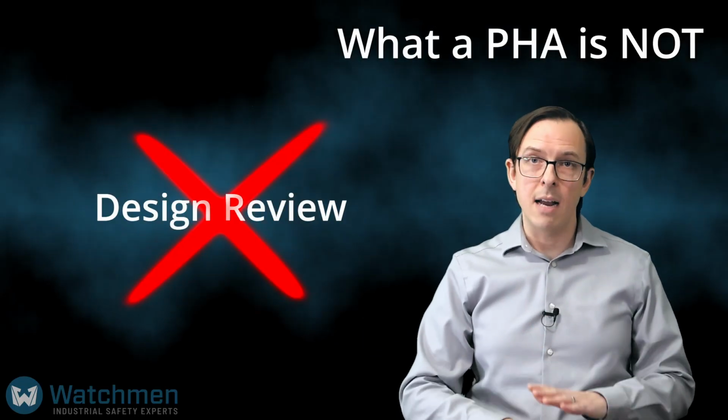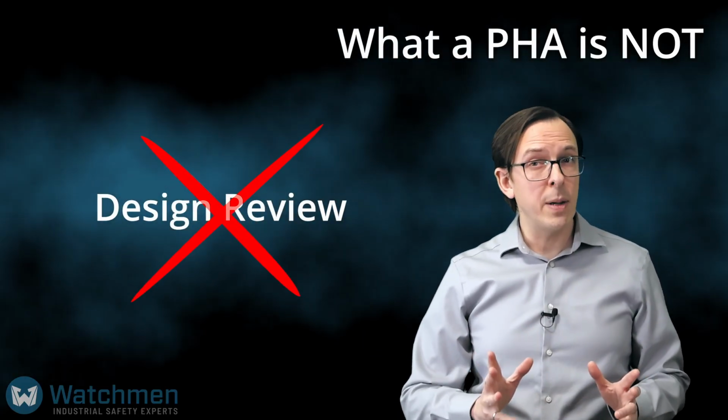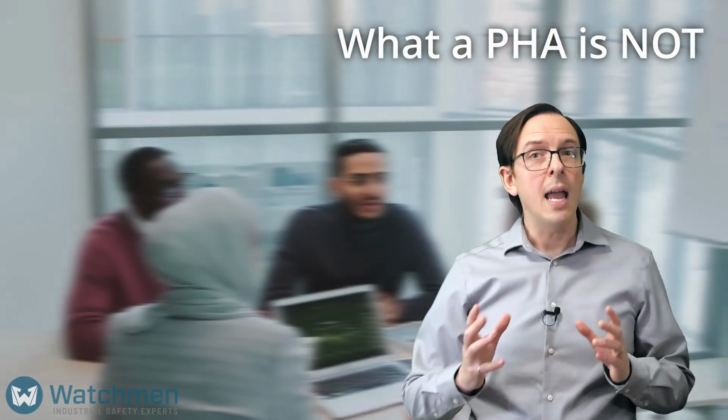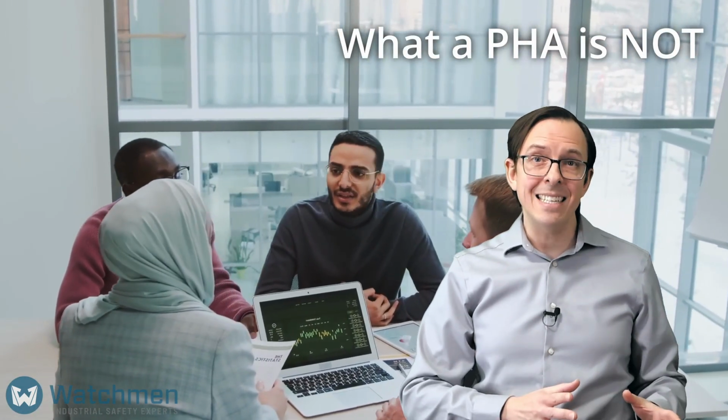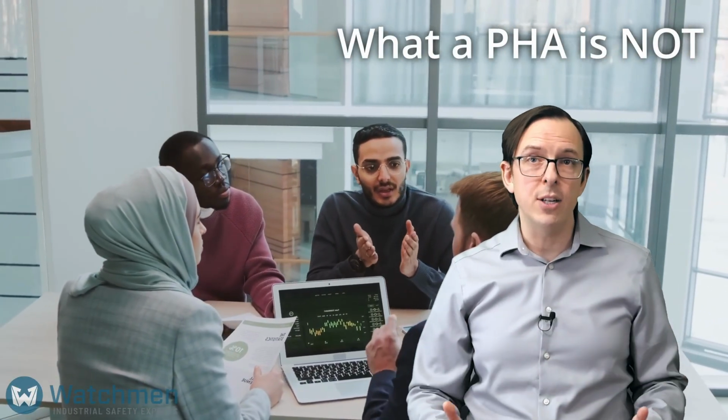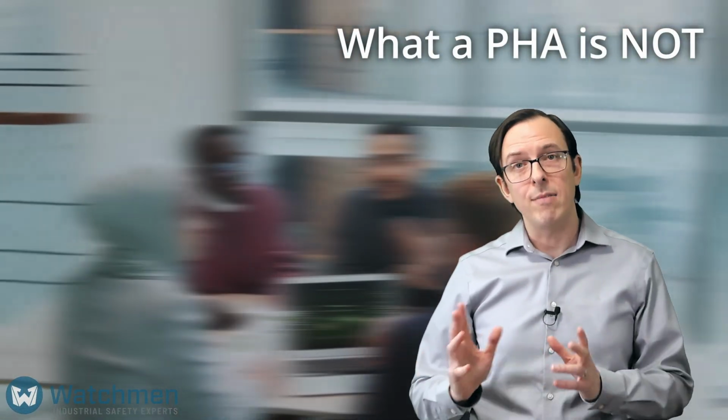PHAs are not design reviews. The design should have been reviewed by a multidisciplinary team prior to the PHA. If small changes to the design are needed, they can be incorporated into the session, but large, disruptive changes may require postponing and rescheduling the session.